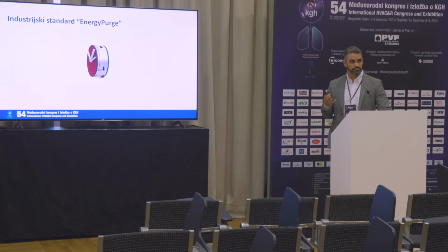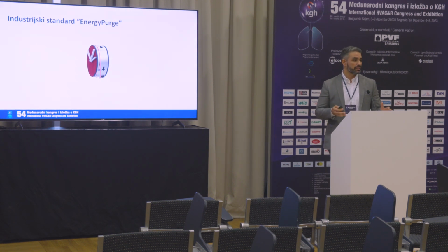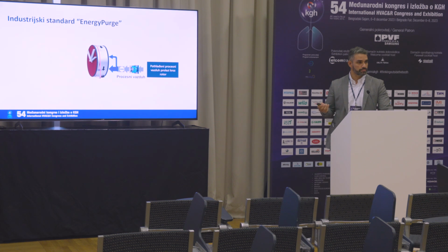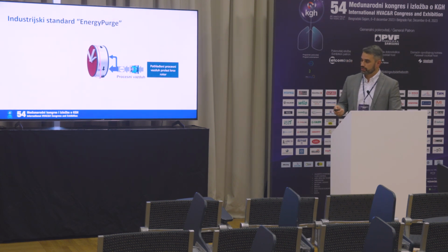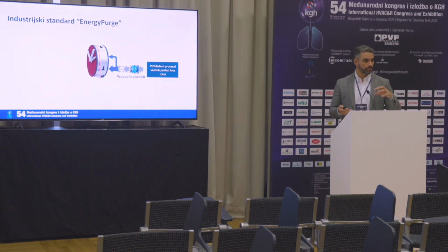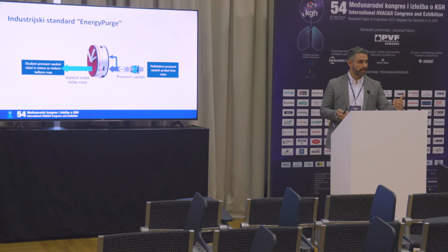And most of you are aware of the industry standard, which is the general adsorption wheel itself. So basically, we have a part of the process air that is pre-cooled going through the rotor. The rotor is cellulose paper impregnated with silica gel. So the molecules of water are being kept on the surface of the silica gel. And on the other side, they are being supplied to the room as the air with low dew point.